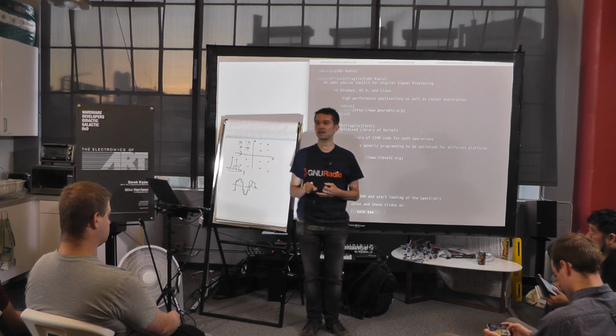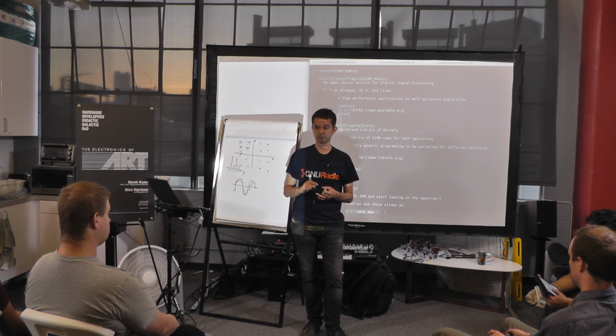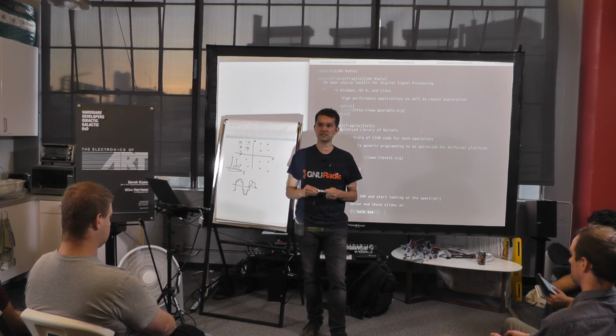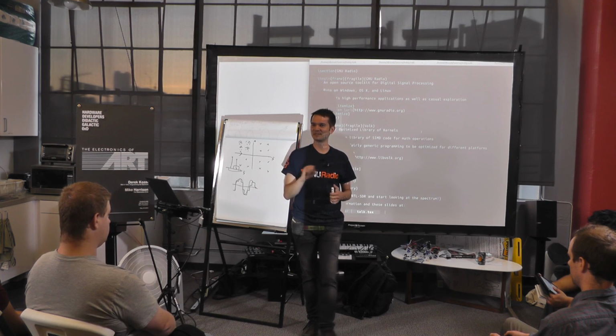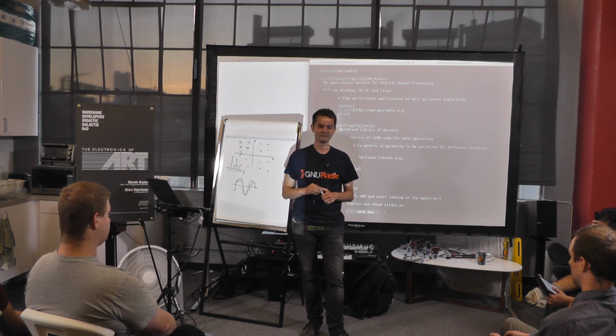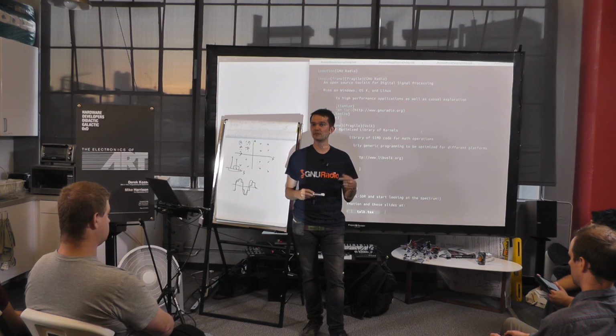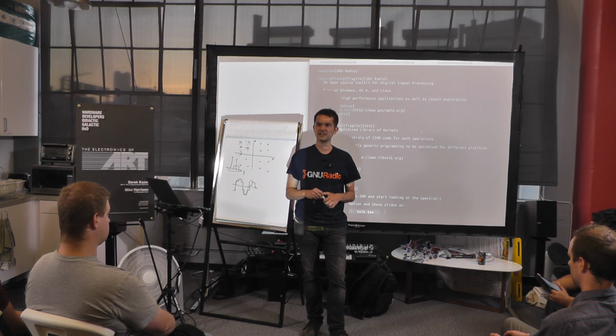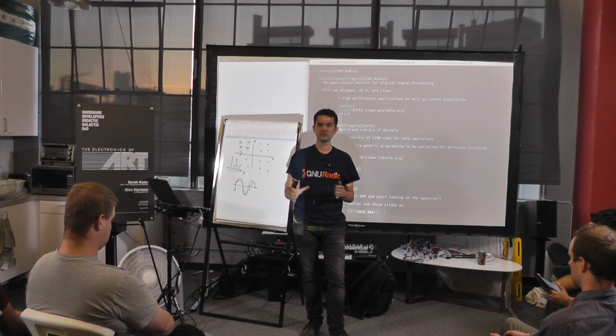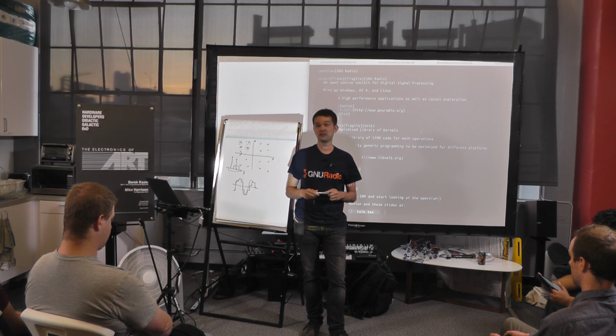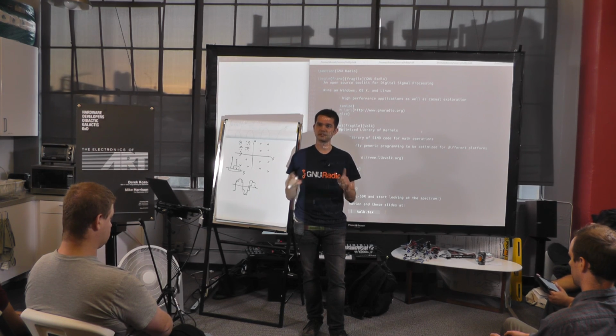The BladeRF is also not a bad choice at all. They have pretty good software support. It's a little flaky in spots, but it is quite good, and it actually beats ours in one or two spots. That hopefully will be fixed by the end of the week because I found the problem. Until very recently, they could only accept a rather odd reference frequency. So they can finally take in a 10 megahertz reference, which is kind of the industry standard. So if you're just playing around, or if you just want something casual, you can save $200 and go with the BladeRF. The HackRF just wouldn't work for you. It's not fast enough, and it doesn't have the type of stability and performance you need.